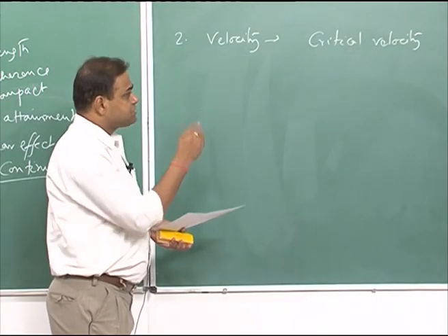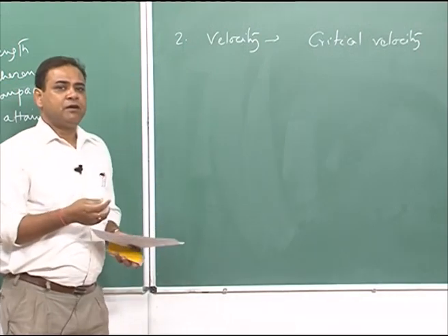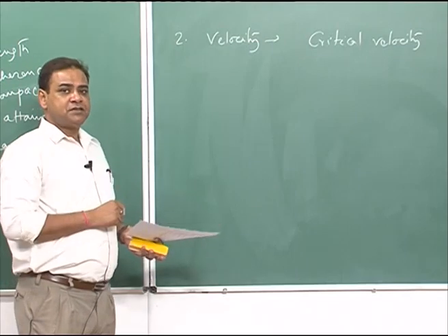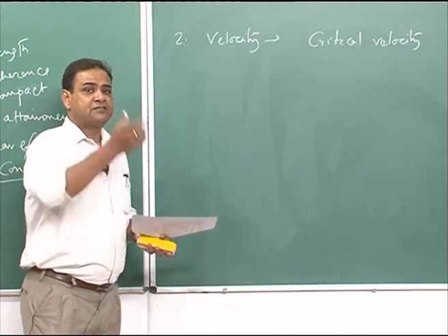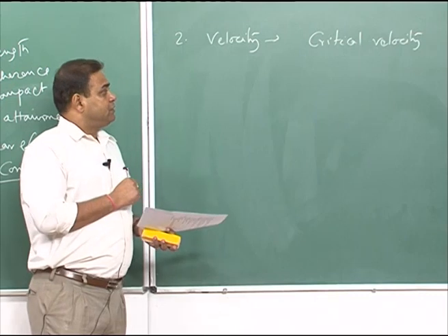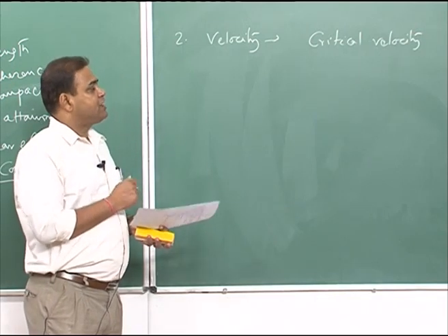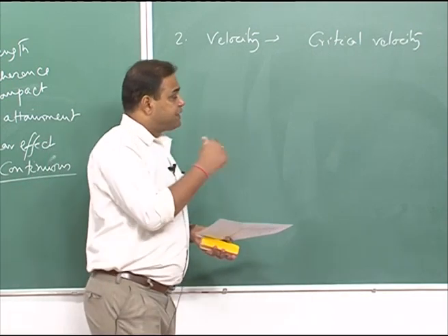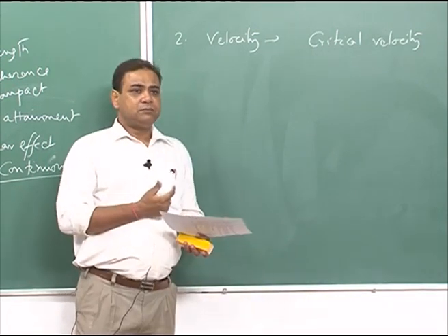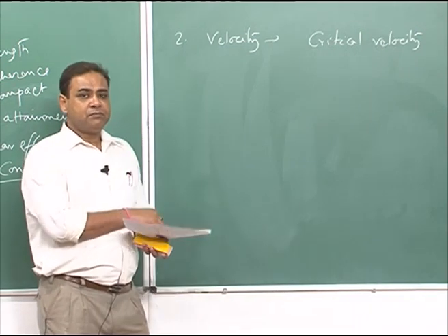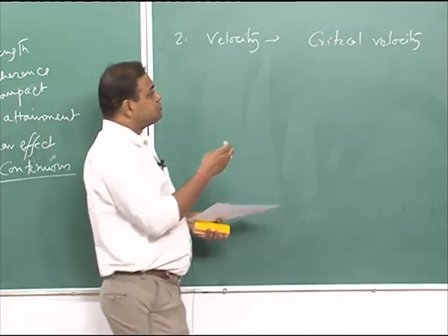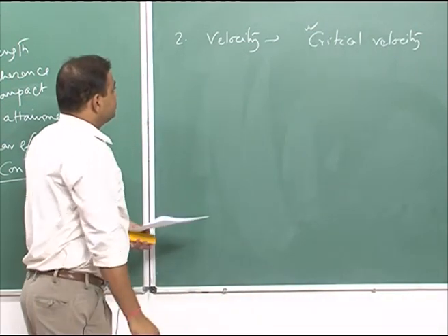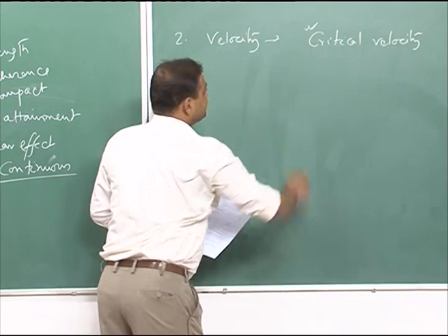Before the critical velocity, the corrosion rate would be very sluggish, but once the critical velocity is reached, the corrosion rate would enhance quickly. Why does that happen? Generally, it is related to a breaking down or dissolution of the passive film, which would lead to enhancement in corrosion rate. So, the critical velocity is an important issue.